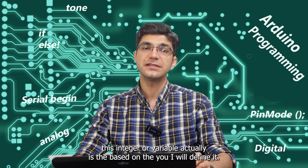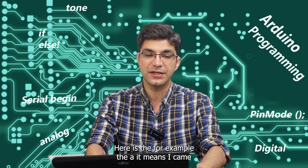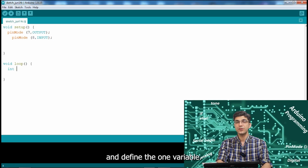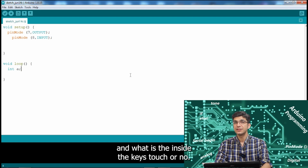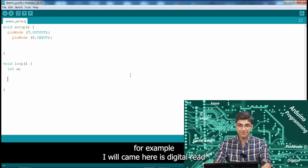We define it in the code by int. The name of this integer or variable is up to you. I will define it here, for example, as a. It means I came and defined one variable. The name is a. Now I want to read the input pin and see what is inside. Is the key touched or not, and after that we make the decision based on whether the key is touched or not. For example, I will come here: digital read.